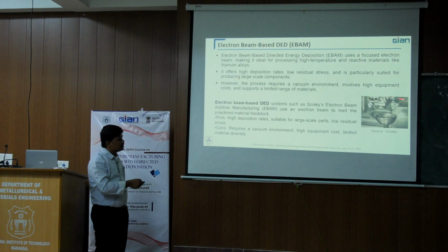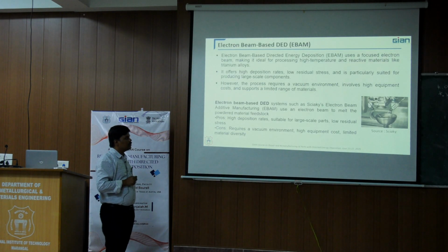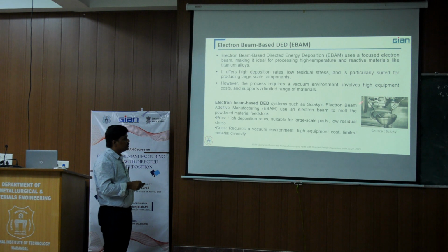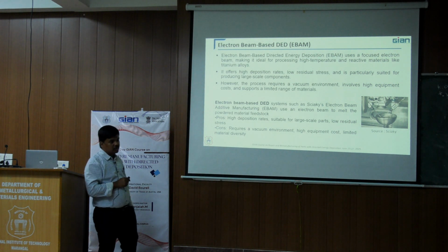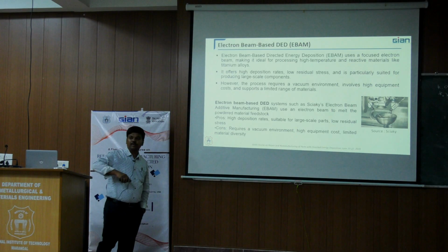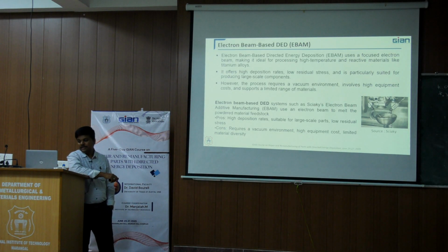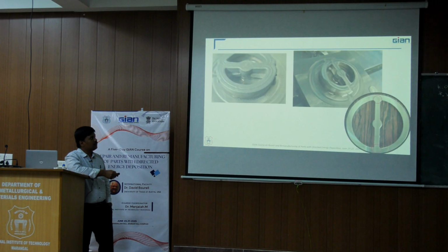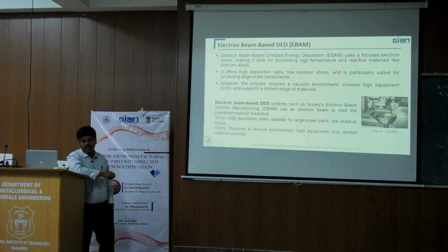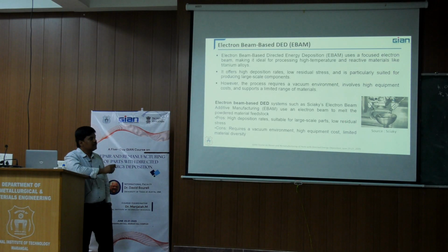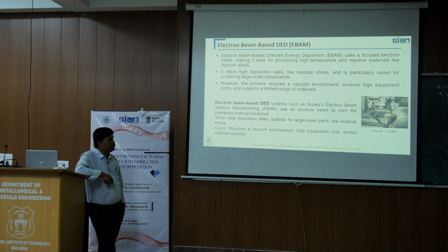But if you see, a lot of satellite particles are sitting on the surface of the part. But if you see the finish of the part made by the electron beam, it has a very good surface finish and also low residual stresses in this EBM process compared with the laser DED process. And we also have a high deposition rate compared with the laser DED process. That's why it is suitable for large-scale components.